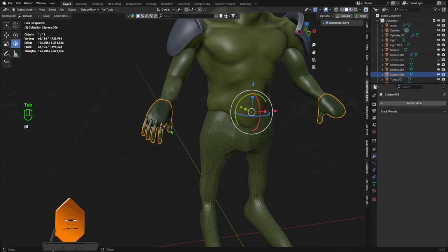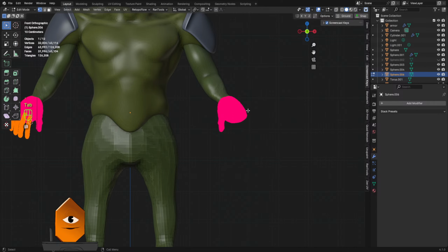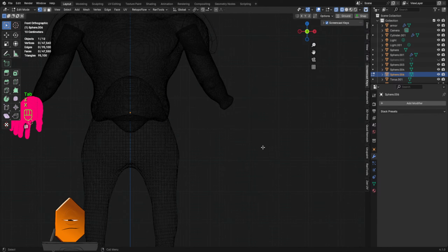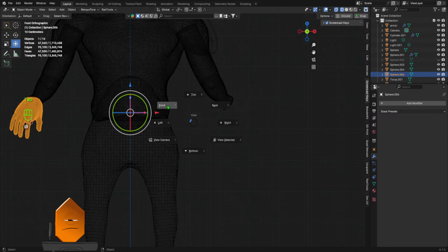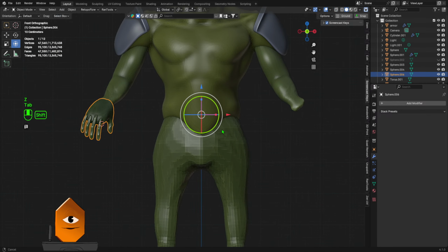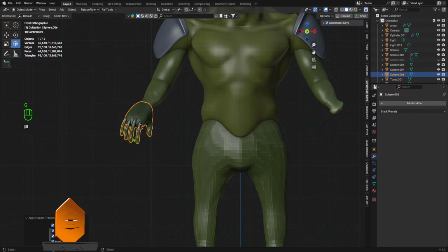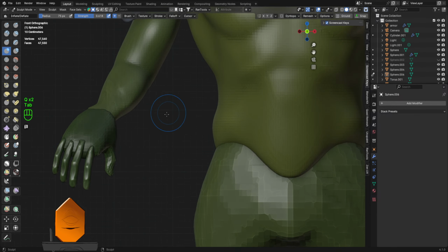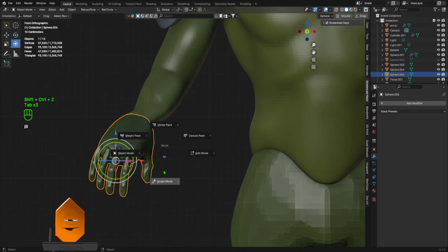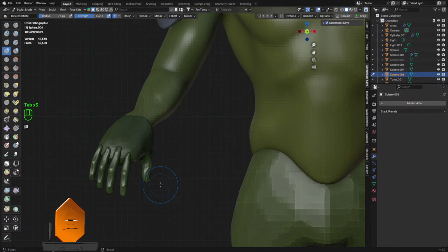I'm not. Let's actually do this. Let's go to the front, edit mode, wireframe, delete faces. That way we only have one to contend with. Solid. Okay. All transforms origin to geometry. I think that was way too much. This is why sometimes when you're doing remeshing, it's good to just use your mouse. Then I can kind of control it.